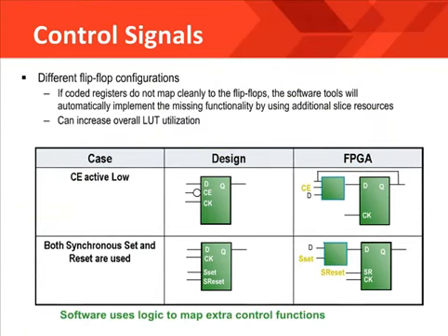As I mentioned earlier, your synthesis tool can map clock enable and synchronous set or reset functionality to a LUT input. This is very powerful for being able to group registers into the same slice, since all the flip-flops are required to share the same control signal. In this example, we see how a clock enable and a synchronous set or reset is mapped to a LUT input. Now this is very helpful, but a job only your synthesis tool can do. But if you build with an asynchronous set or reset, then it can't happen. In that case, the asynchronous set or reset would be forced to a register control port. Likewise, if you build with an active low control signal, the LUT will be required to invert the control signal.